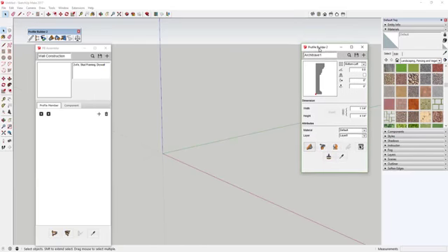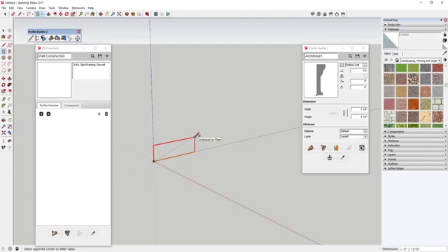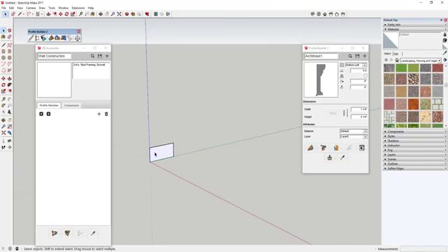That's really easy in Profile Builder. All you have to do is come in here and draw your shape. In this case, we're going to draw a box that's 4 inches, 2 inches, and then hit the enter key. I realize the actual dimensions of a 2x4 aren't 2x4, but for this exercise, it'll be good enough. Now that we've drawn our profile, which is what's going to get extruded, we're going to select it, go into the Profile Builder section and click this new profile. And we'll just call this 2x4 plate and hit OK.